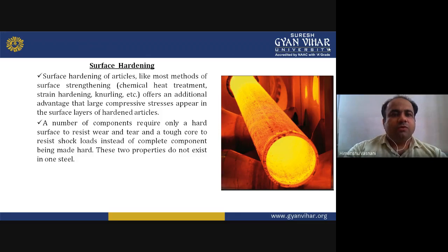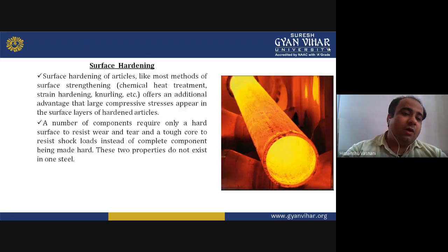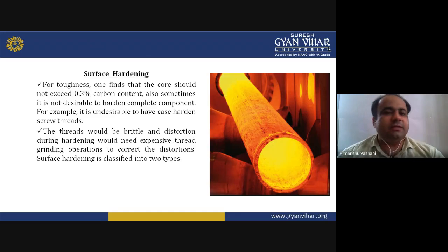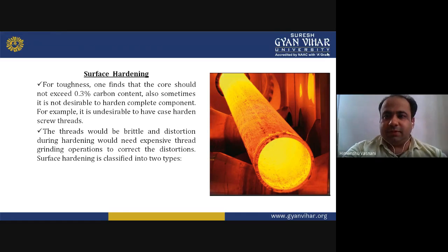For toughness, one finds that the core should not exceed 0.3% carbon content. Now we are talking about the experimental data. They say that for toughness, the core should not exceed 0.3% carbon content.